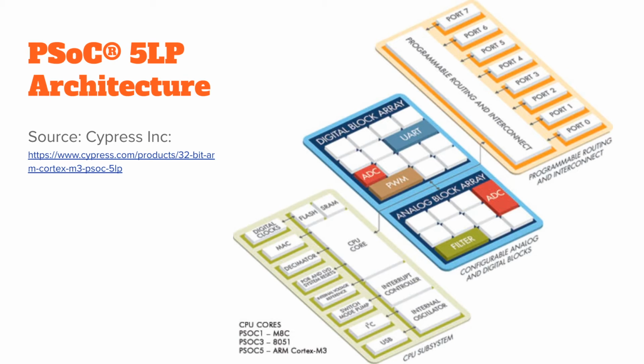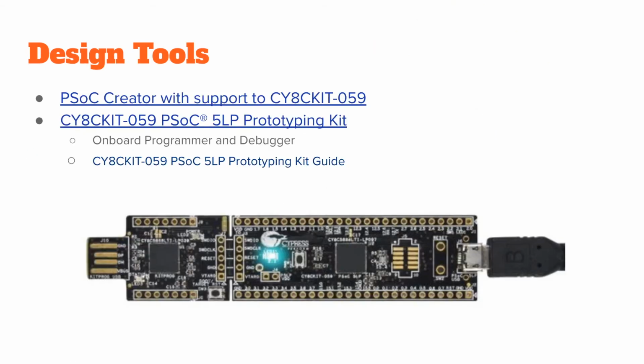So 5 times 8 is 40 pins, and it gives you some freedom in designing the chip or the program, the PCB layout, so that you can connect the pins in various ways, so you can minimize the amount of vias and that kind of thing on the printed circuit board.